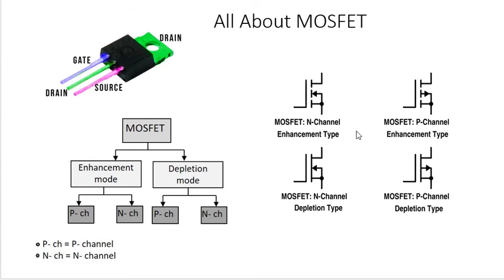In n-channel, the channel is of n-type material and it has nearly twice the mobility compared to holes. But in case of p-channel, the channel is of p-type material and holes have half the mobility. So you can pass twice the current in the same area with n-channel MOSFET, but with the p-channel MOSFET you will roughly be able to supply only half of the current of n-channel MOSFET. So we always try to use n-channel MOSFET in power electronics.